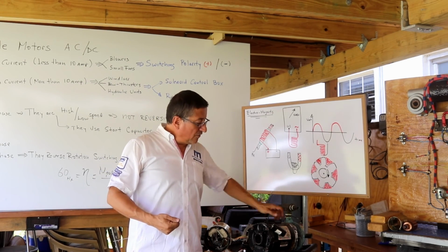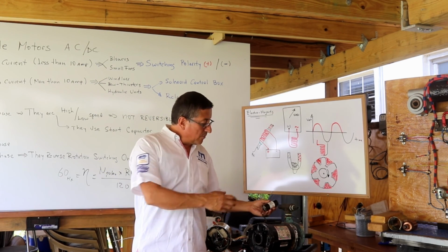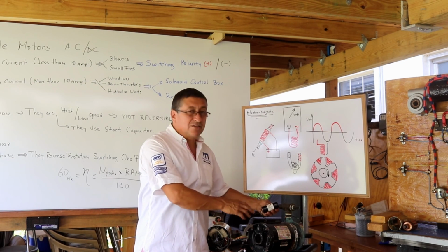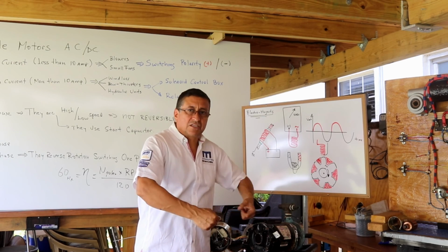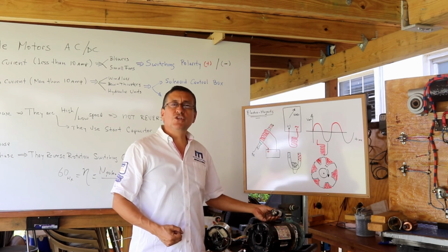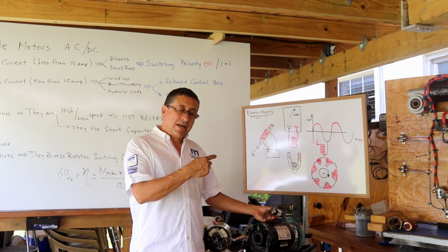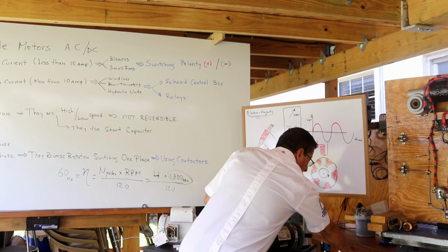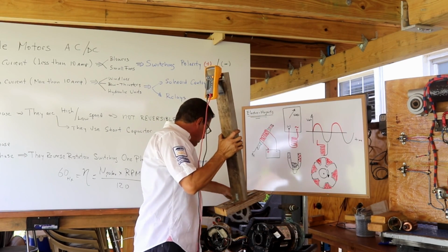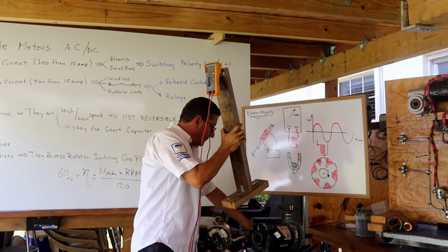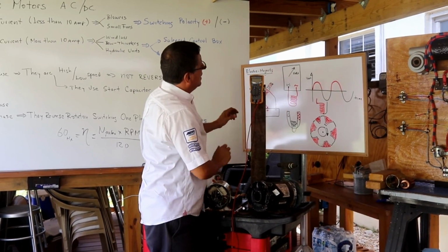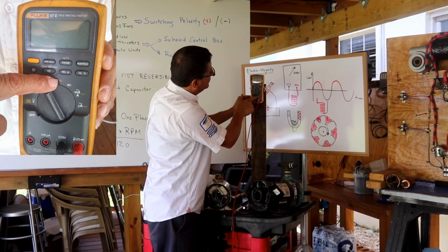If you remove the cover and you check the capacitor, probably the capacitor is exploded, or too hot, or expanded because it is damaged. What is the procedure to check the capacitors? Right now I am going to explain the procedure to check the capacitor. To check a capacitor, you need a voltmeter, and you need to select the voltmeter in the capacitors function.